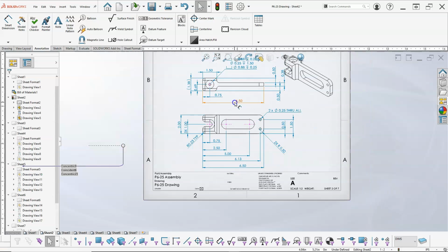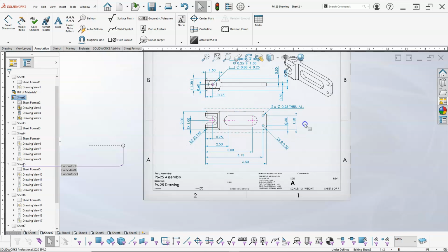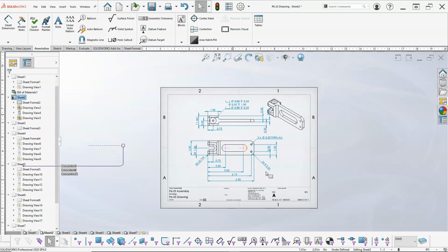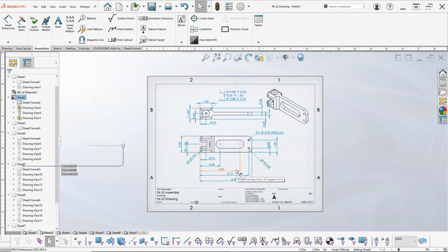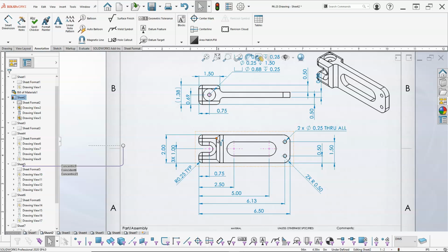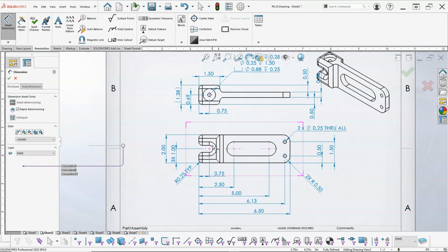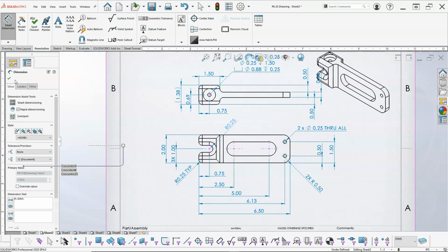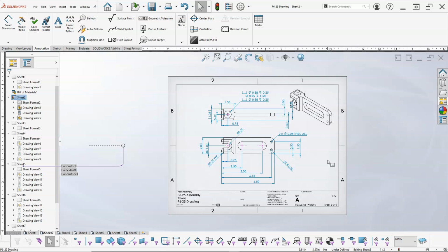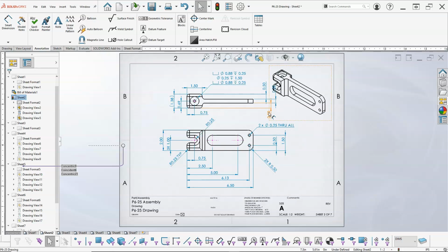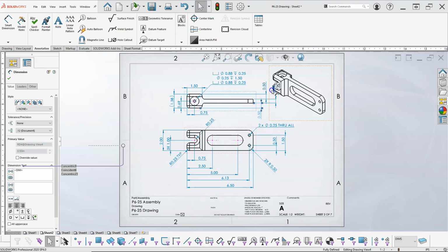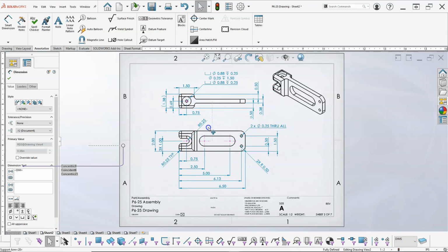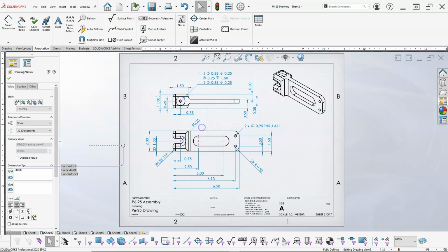Alright, so since that one's still there, we'll go ahead and take that out. Alright, so when we do the tolerance and stack ups, we go back through this, look at what needs to be set to 3 place decimals, what our critical dimensions are, and it looks like I missed a radius, so that one's going to be pretty critical, and it's going to have to match up with the bar. Let's go ahead and drag some of these back in. Oh, I must have drug it that way just a little bit. Okay.